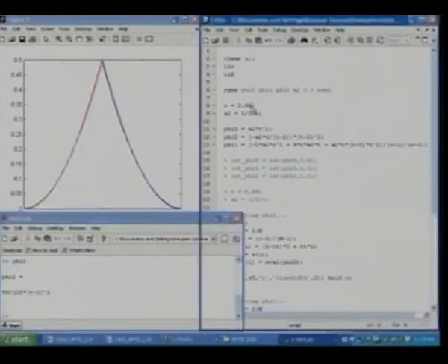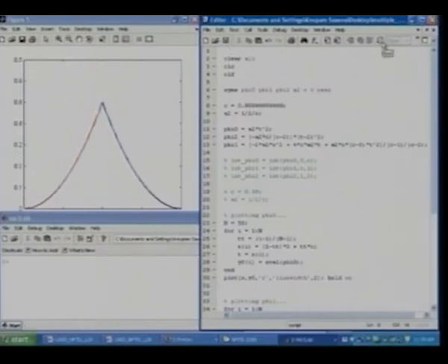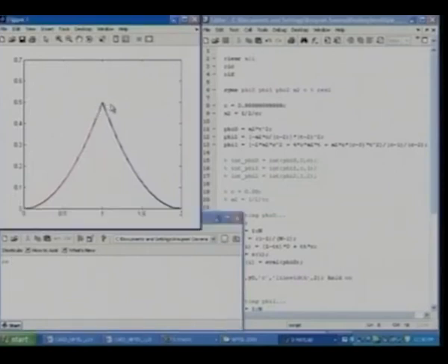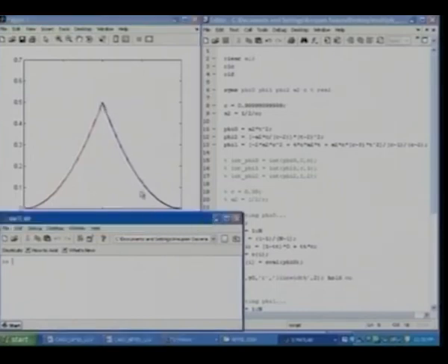Let's now make this c value very close to 1, but not quite 1. You see a clearly defined peak here. At this junction point, initially you would observe that the B-spline basis function was C1 continuous. Now you would clearly observe slope discontinuity here, but position continuity is still maintained. You would also observe that the green segment has vanished. It's only phi 0 and phi 2 that remain. Well, has the green segment vanished?